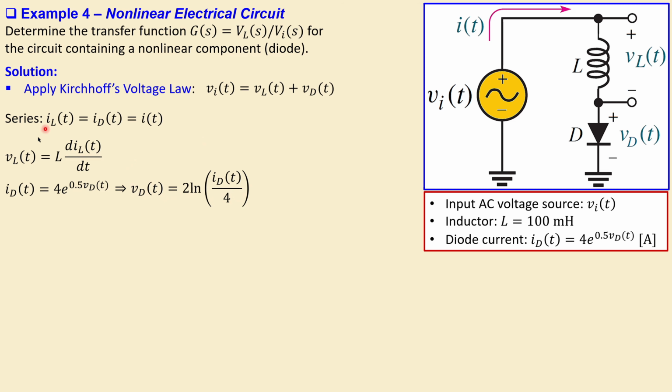If I now substitute this in here and also this in here, so in this VI expression, I will get this. Now this is definitely nonlinear. We have an ln here, which is some function of that current, which is definitely not linear. So we need to linearize this. So sort of the linearization of a differential equation we have discussed before, now in action in an actual system, electric circuit. Let's call this equation number 1 because we need it later.